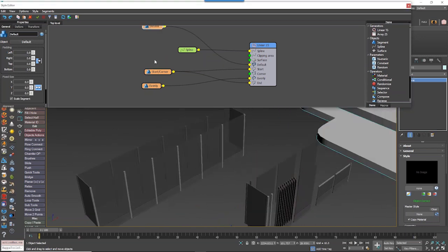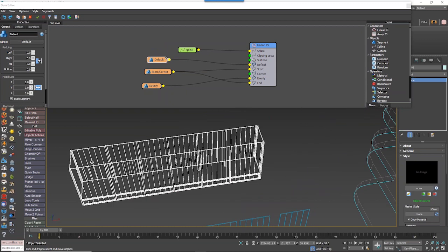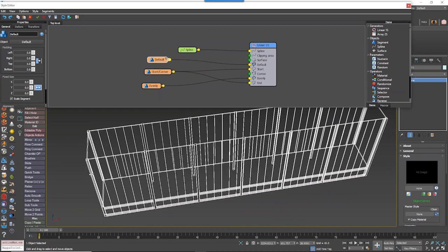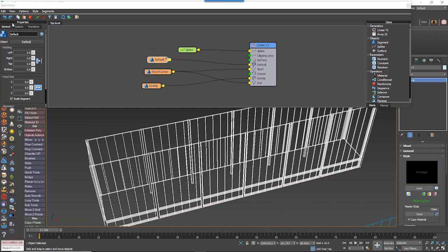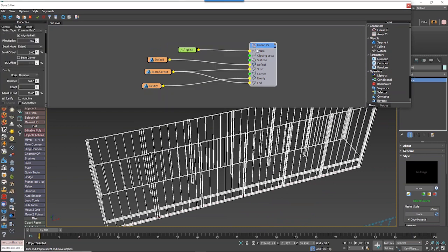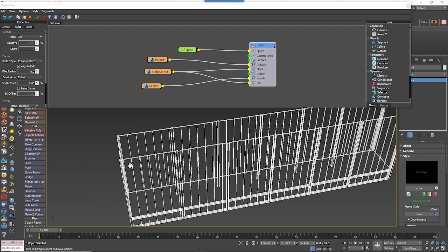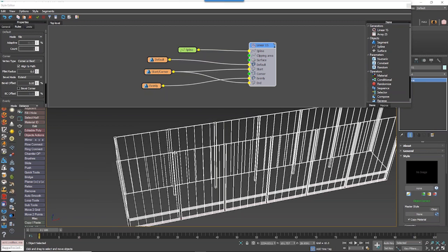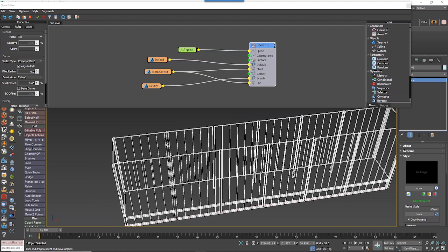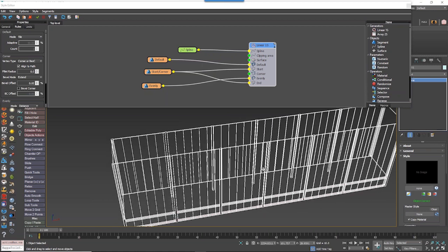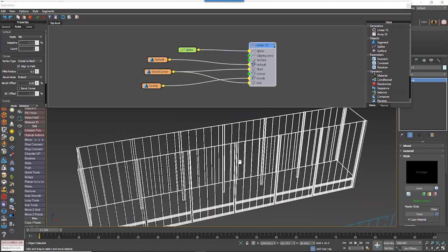A couple of other things that I would change. It's hard to see in this one, but the way in which this is distributed between the segments is determined, sorry, in a generator, it's determined by the default section here. And by default, it's set to tile. So what happens then is this will just be placed, and then when it hits one of these evenly segments, it gets sliced if it's shorter than the distance between the segments. So basically, it just repeats one after the other, and it gets sliced wherever it hits an evenly or a corner or an end segment.